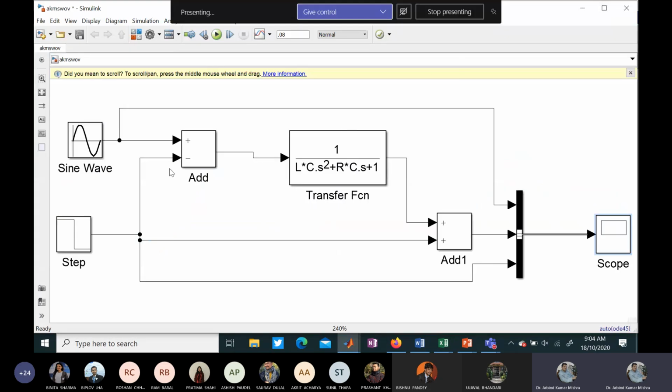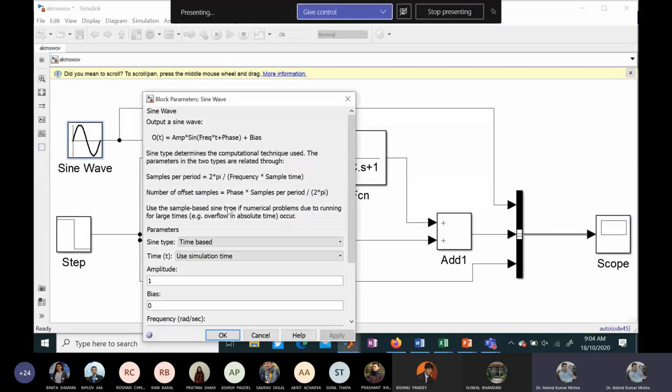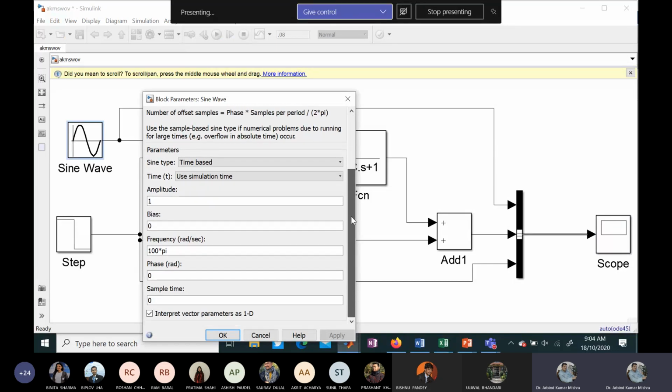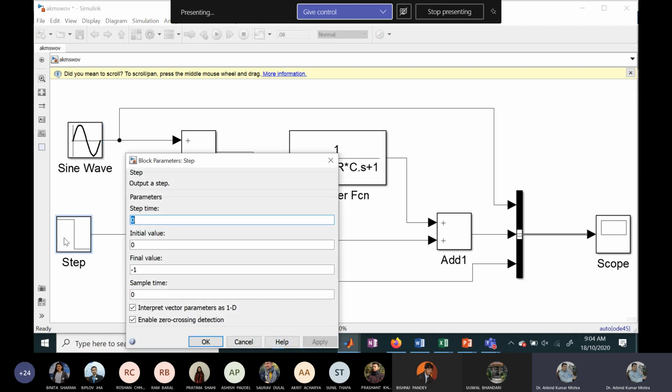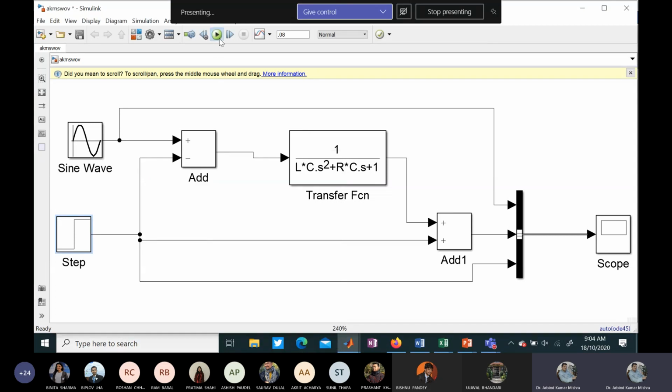Now change one thing, the switching instant itself. If I want the switching instant to be at the peak value, I can simulate it by saying that instead of this sine wave, this is a cos wave. I just put a phase difference of pi by 2. What does it mean? The sinusoidal wave starts at the peak itself, and the switching instant is the peak itself. And what was the trap charge? Trap charge here is initially considered 0, no trap charge, and now plot it.